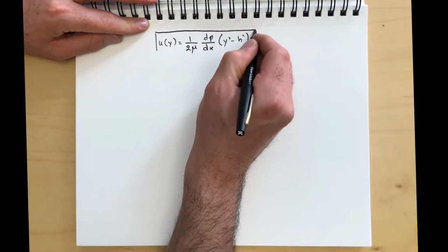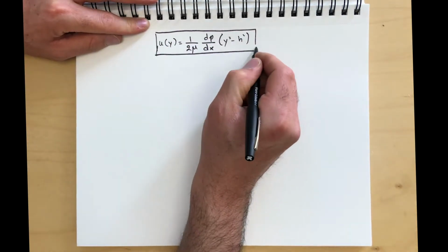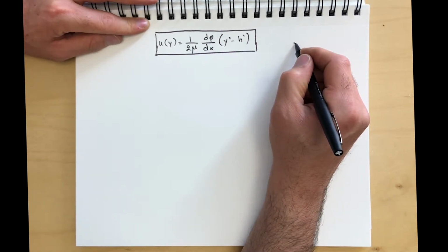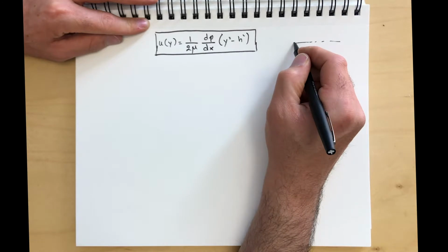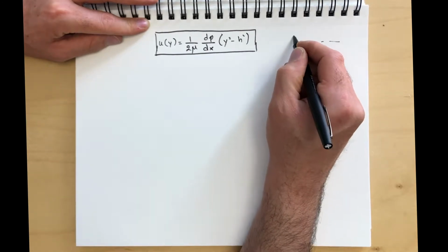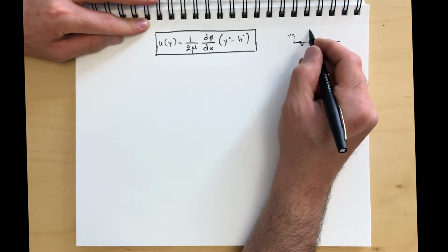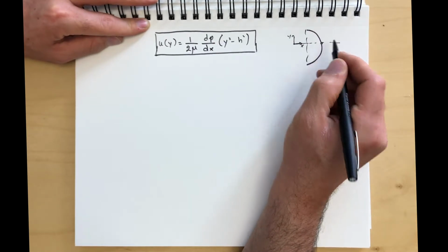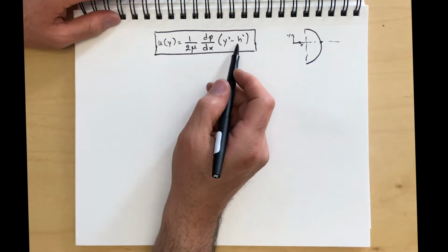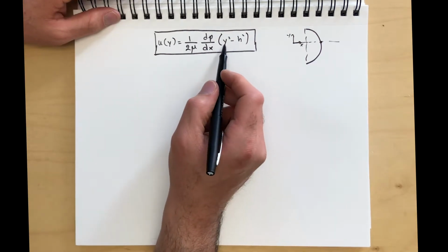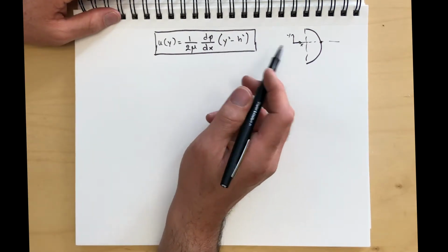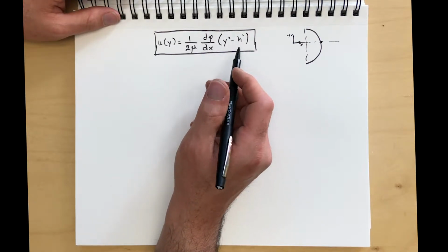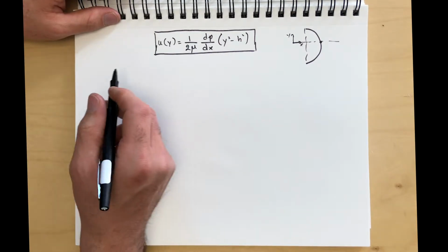And indeed, if you plot this from minus h to h, with x and y, you're going to get this nice parabolic profile with the maximum occurring at the center line. Maximum velocity at y equals 0. We haven't said anything about dp by dx, so let's show that dp by dx is a constant.